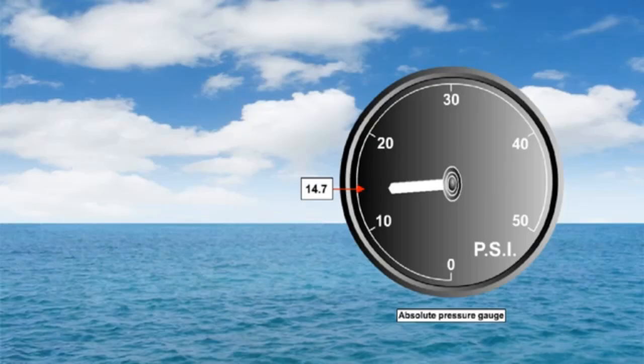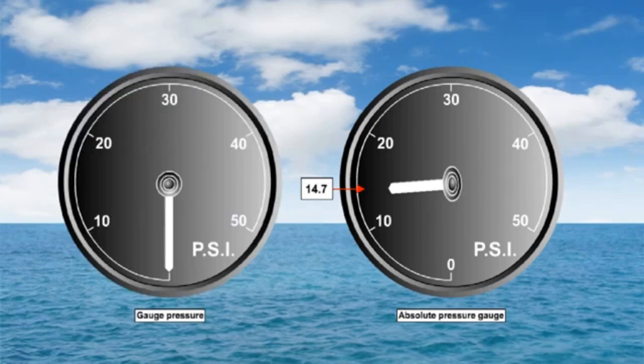When we're discussing pressure measurement, we must use the following terms: absolute pressure and gauge pressure. Absolute pressure is measured relative to absolute zero pressure, the pressure that would occur at absolute vacuum. Thus, the absolute pressure on the Earth's surface at sea level is the atmospheric pressure, which is 14.7 pounds per square inch. The more usual pressure measured by most gauges is called gauge pressure. Gauge pressure reflects an adjusted pressure that reads zero at the Earth's surface.